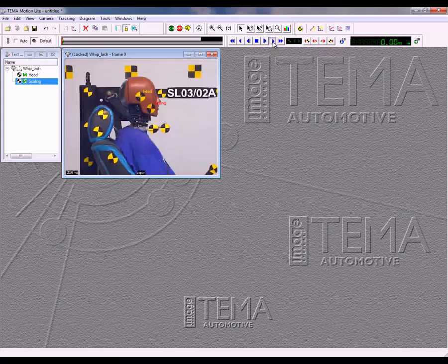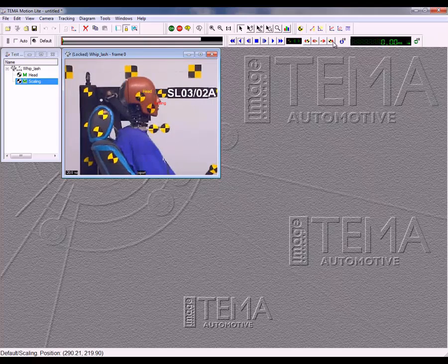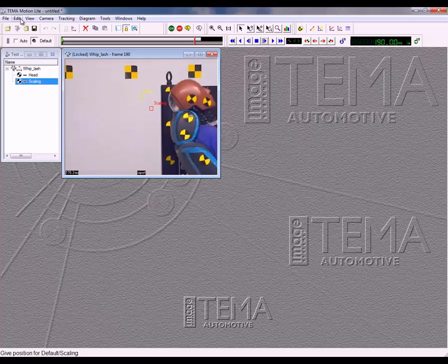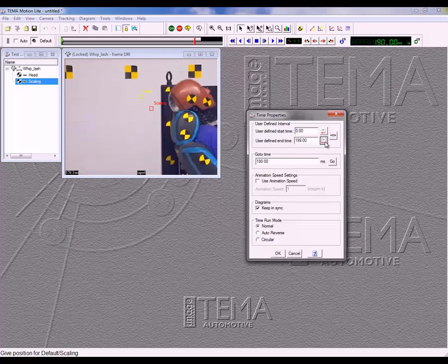The blue navigation buttons are video controls. No tracking is done. The 4 with targets on are the tracking buttons, 2 forward and 2 backward. The inner ones track only 1 frame and only need to be used if automatic tracking is poor due to poor images. This image sequence goes beyond the point where we can track, so go to the last frame you want to track, then go to the Edit Time Properties option and click on the clock to set the end time for the sequence. This will not edit the image, only restrict the visible portion.